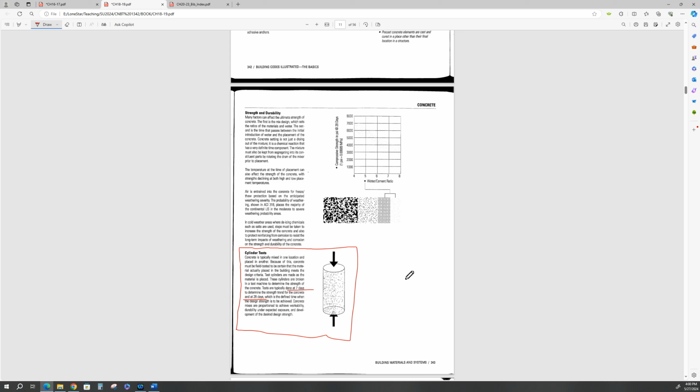Now, when you're doing a bunch of high-rise stuff where you're having form work, you're always looking for early strength so you can remove the forms underneath and start building the form work on top. And at some point in time, then you can start wrecking the forms underneath, but you still got forms up here. But you got to be really careful and balance at 7 and 28-day strength.